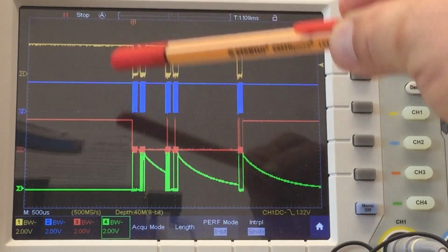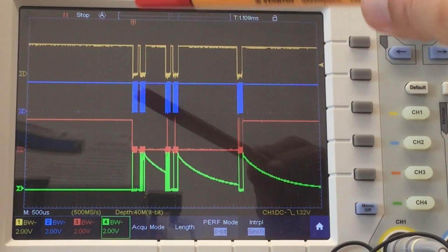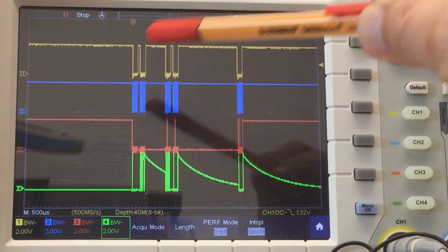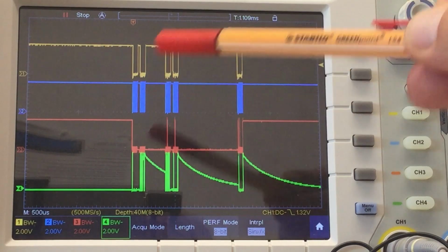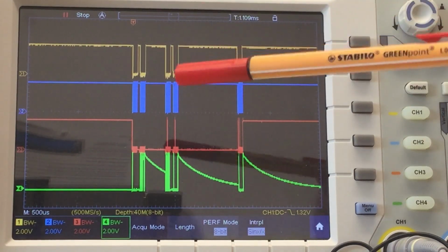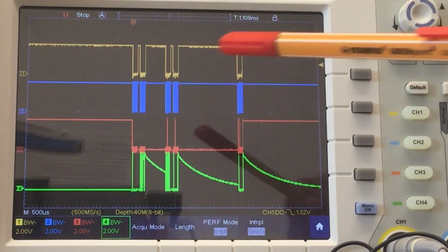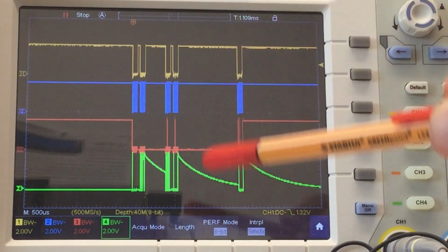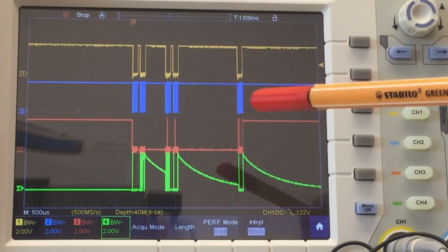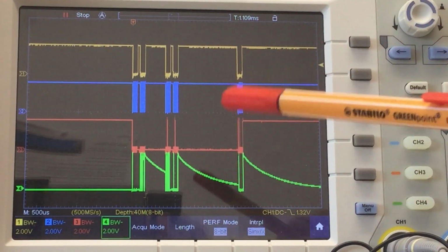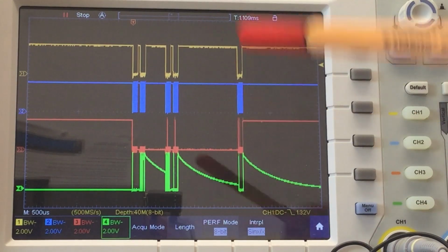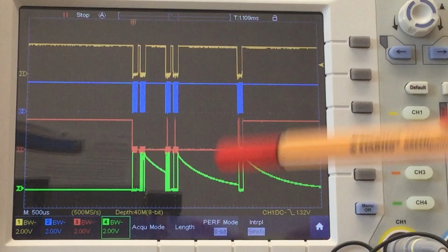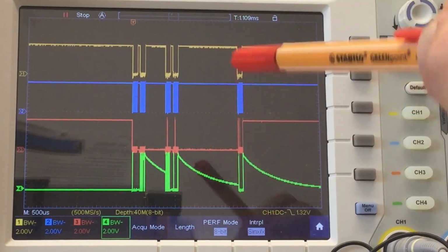So I read here in 2 transactions my angle, and I got an error bit set, so I read the error register to see exactly what's the problem. I printed that out on the serial monitor. And then I sent a command to the config register to reset all the error flags. Why? Because some error flags need explicit resetting to get rid of them. Let's zoom into that thing.